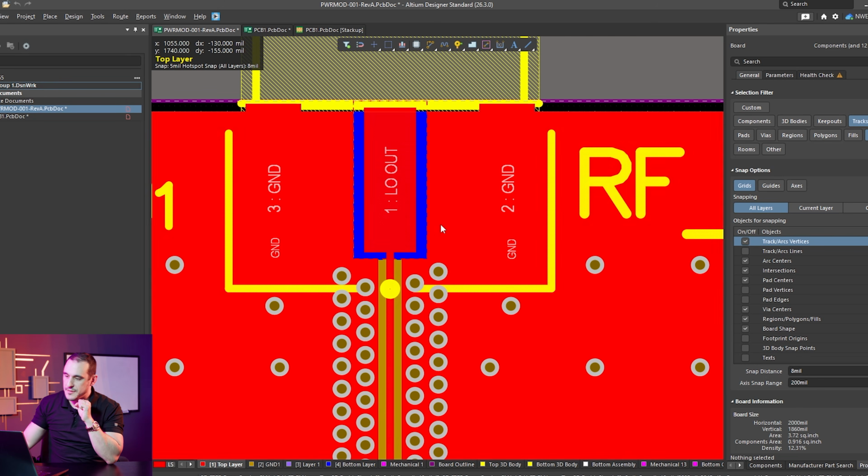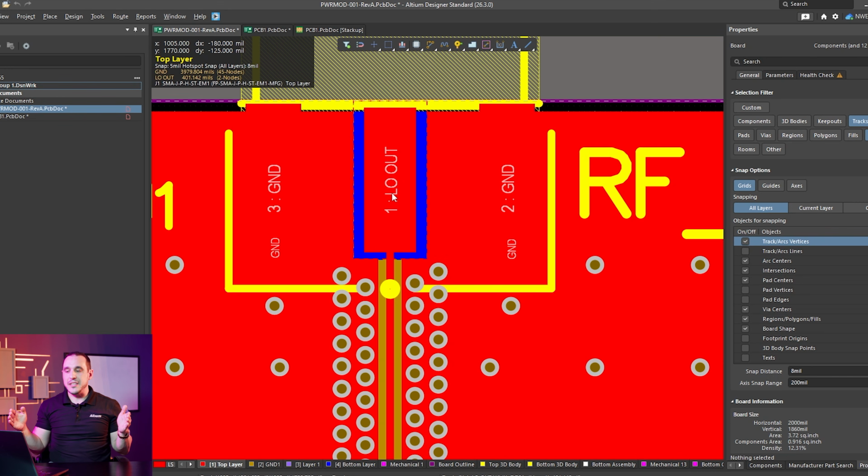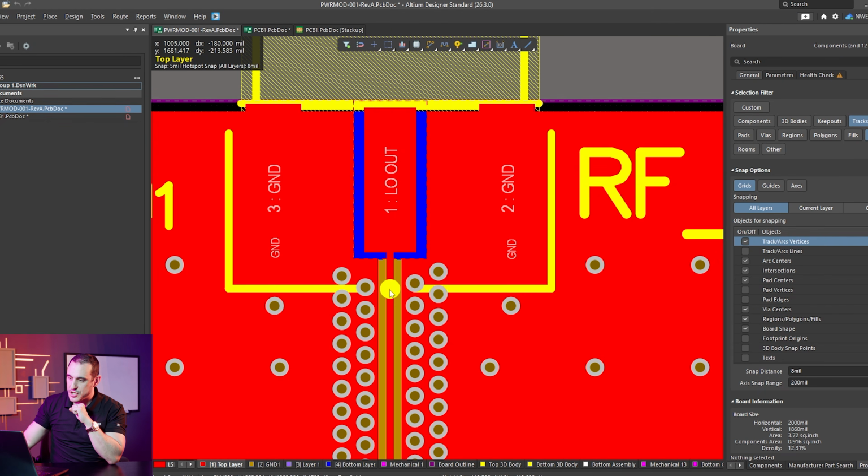Now the last thing that I want to bring up is the transition between these two elements in the PCB. So here we're going from a narrow trace to a wide connector. And I think it's natural to ask, do we need to place a taper in this design between this trace and this pad? Well, theoretically, you shouldn't need to, but it's always worth checking if you have some simulation capability. So when you have simulation capabilities, you can place a taper and you can compare the return loss with the taper versus without the taper.